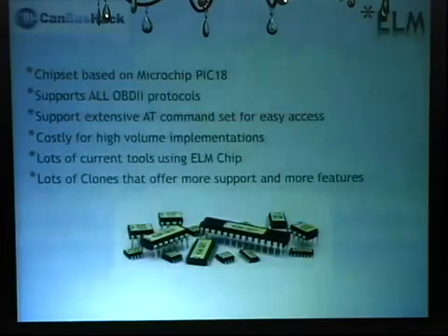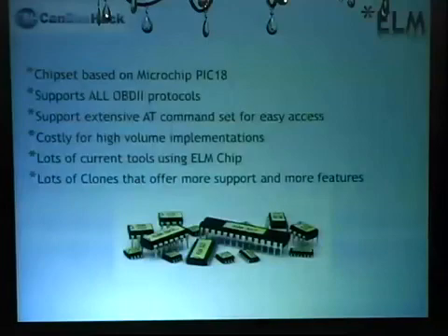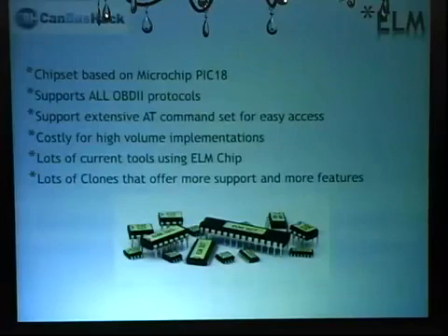Here's the ELM chipset. Supports all the OBD2 protocols. You have to sort of make your own. It's the chip itself. You have to cobble together your own devices, but it's AT commands. It's a little costly for high volume implementations, but the good news is there's a lot of little clones out there as well too. So it's a very de facto standard for creating and talking to the CAN bus.